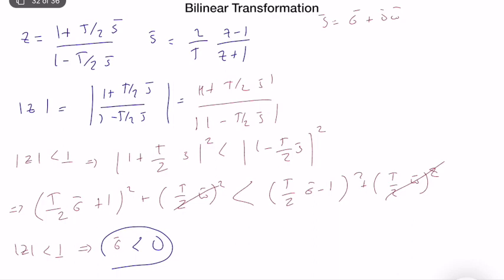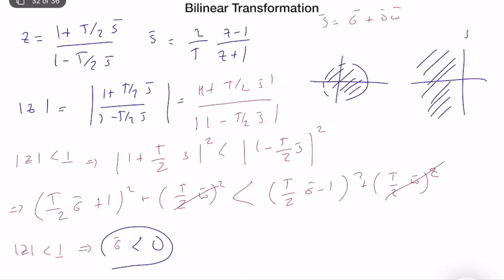You can look at the detail. Okay, so it is kind of an expected result because z bar less than 1 means that we are limited to the region inside the unit circle, which is the whole stable region, and sigma bar less than 0 is technically the open left half plane. And since S bar is a fictitious continuous time domain Laplace transform expression, mapping a stable region in Z domain to a stable region in S domain is a useful result.